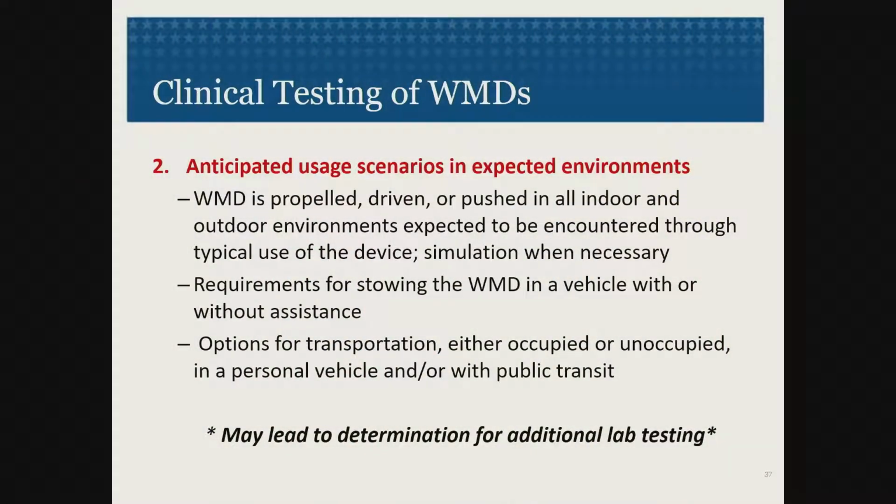And the second area with clinical testing of wheeled mobility devices is in those anticipated usage environments. So again, if it's intended for use in other types of settings than a controlled clinical setting with 12-inch tiles and smooth surfaces, get into those devices and get them out into that environment. We encourage this type of approach, not only for devices that might be presented to you by a manufacturer's rep. We've got the latest, greatest wheeled mobility device, and all of your clients should have one. You're going to jump in that device, you're going to drive it, you're going to push it, you're going to kick the tires, you're going to ask for test reports, you're going to ask for the performance data that's available.